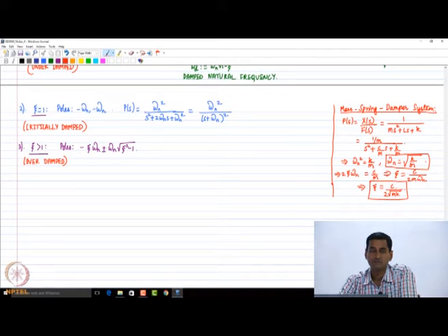The frequency of the system if damping was zero. C was zero. And the frequency at which the system will oscillate. Is it the complete answer, or do you want to add something to it? Even when there is no external force, there should be no external force and no damping. If you consider the free response of the system, and under that you impose the restriction that there is no damping. So I think that completes your answer, right?